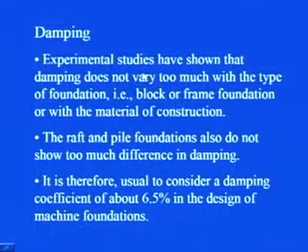Then experimental studies have shown that damping does not vary too much with the type of foundation, that is, whether it is a block foundation or a frame foundation, or with the material of construction. So, whatever the material of construction, be it concrete or any other material, or whatever the type of foundation, be it block, box or wall foundation, the damping does not vary much.